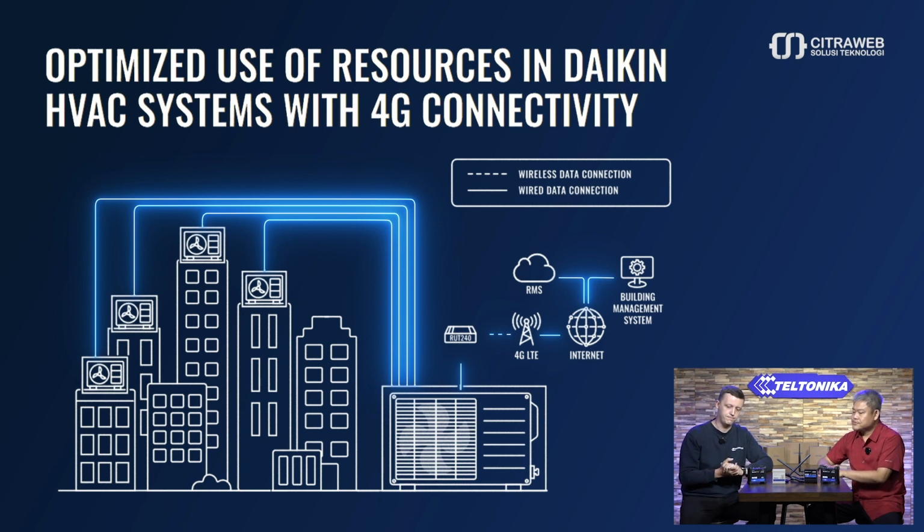In a simple way, basically every AC has a controller that can get some data from the AC. For example, whether it's working or not, the temperature, and an option to check how dirty the filter is, and any other data. So we can turn the AC on and off remotely, make a schedule or do it manually, through RMS connected to the controller, and we can do everything that the controller can do.